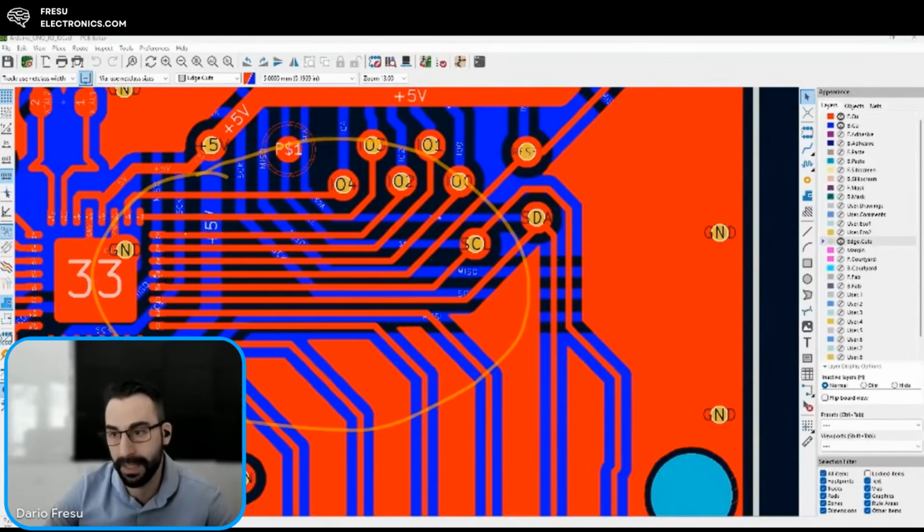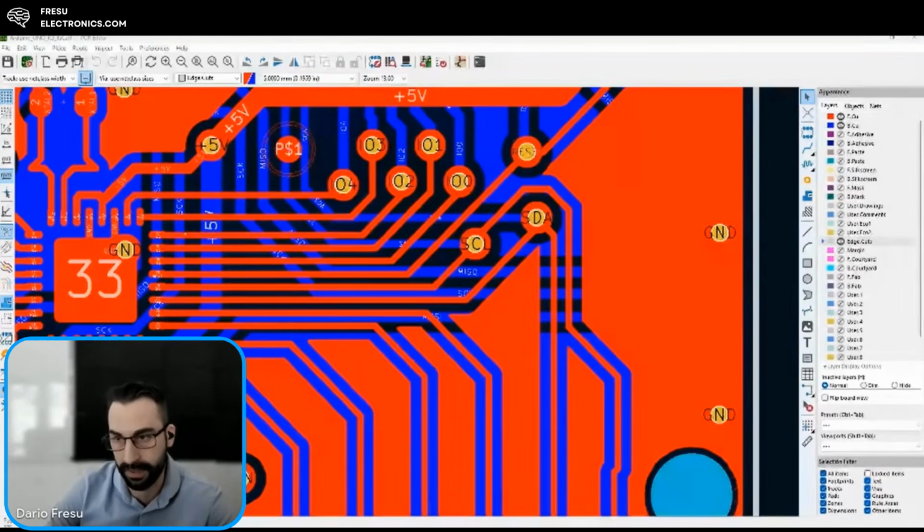In the space in between is going to propagate the signal, not within the conductor. Especially depending on the rise time that I have, it is barely going to see the conductor because of the skin effect. It's going to stay outside of the conductor. So it's the field that propagates within. This is all the problem. So I have zero chance with something like this to pass electromagnetic compatibility test.